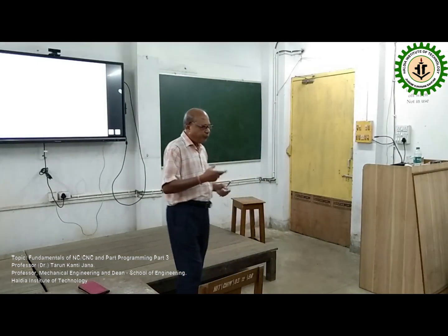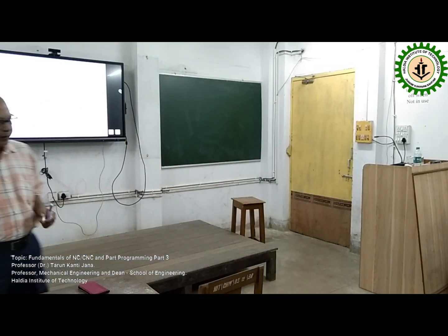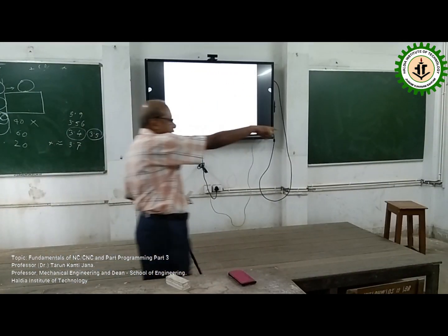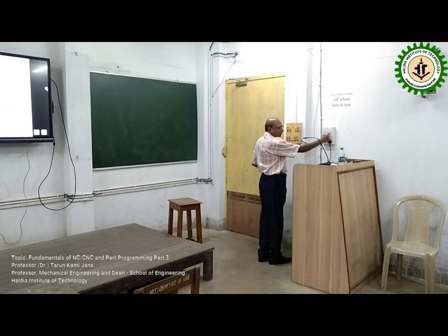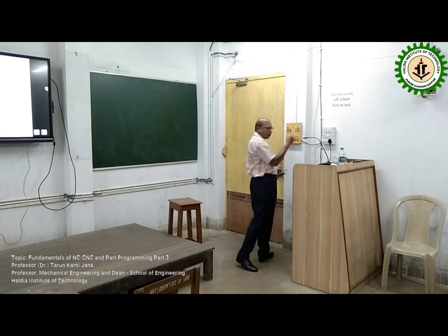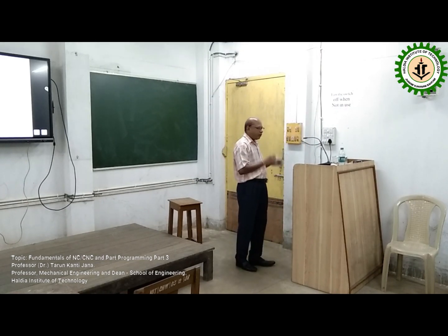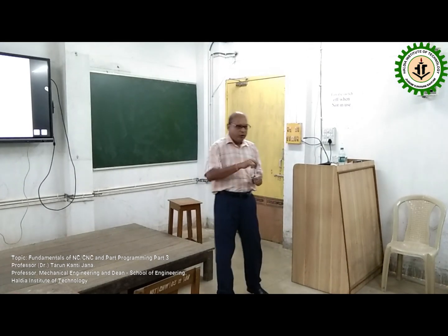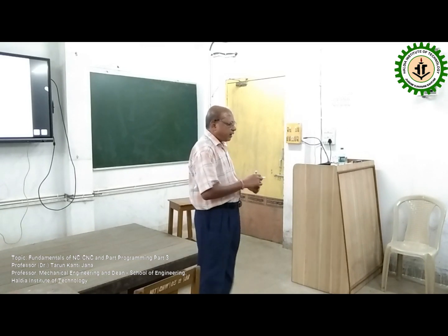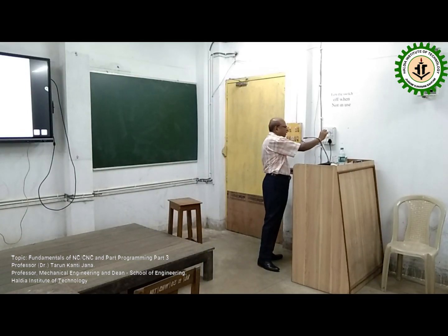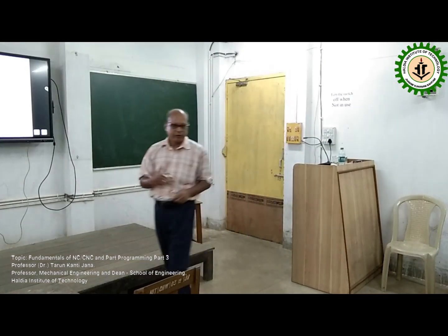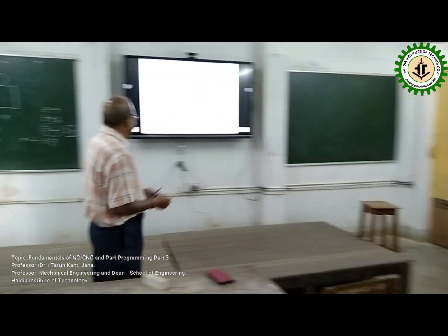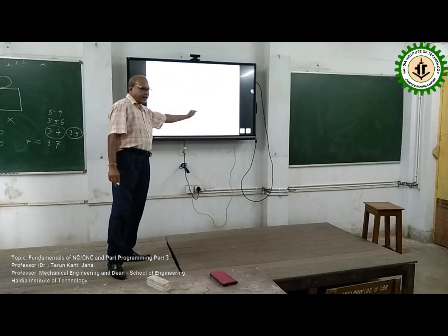So usually we specify some specific attributes as different parameters, and these are daily operations. You can see that all the 4 holes have the same diameter, and of course their depth is also assumed to be the same. So in that case, whatever attributes pertain to one hole will be specified at one location. After penetrating one hole, it will simply shift to the next location and repeat the program. So that will be repeated for 4 different locations. This sort of job is very common in the mechanical fraternity or manufacturing. In this case, we use the peck drilling cycle.